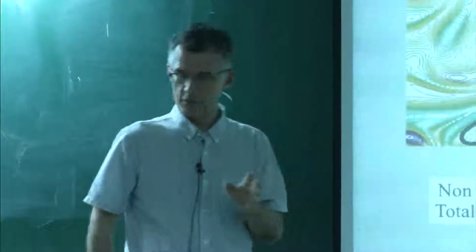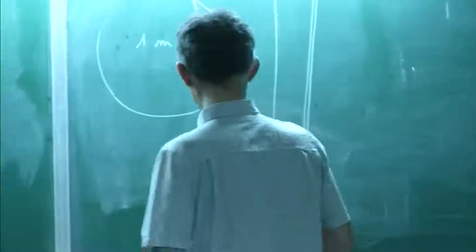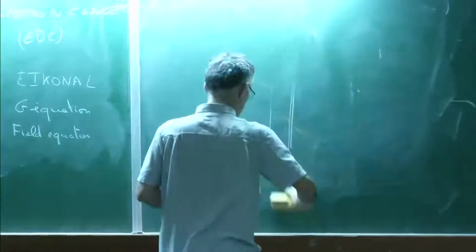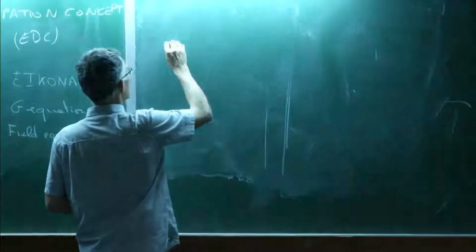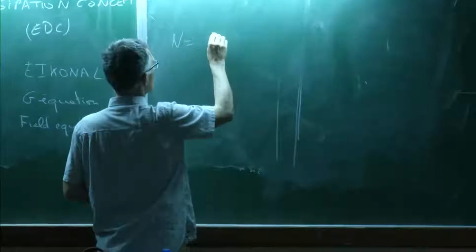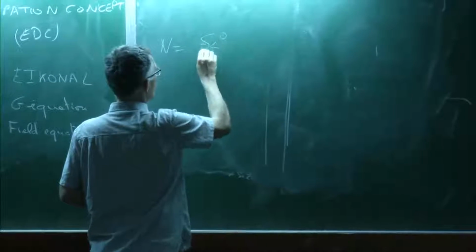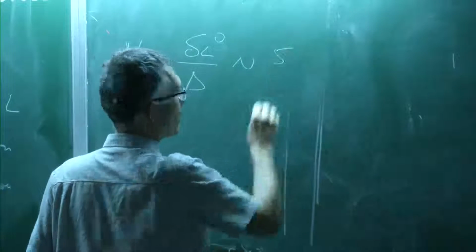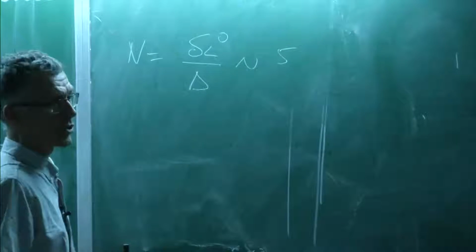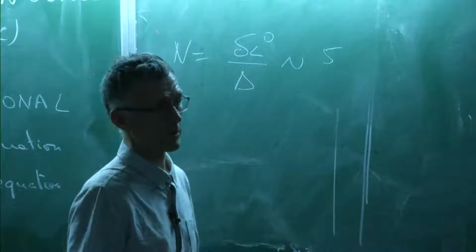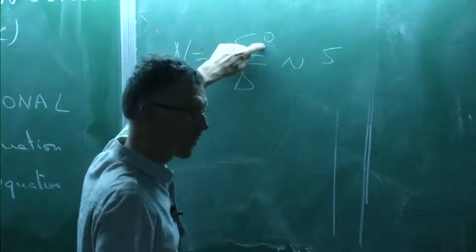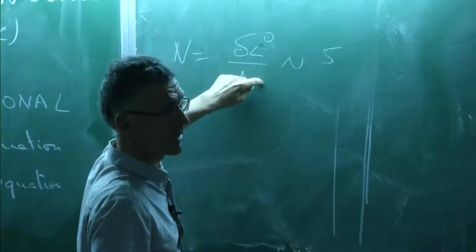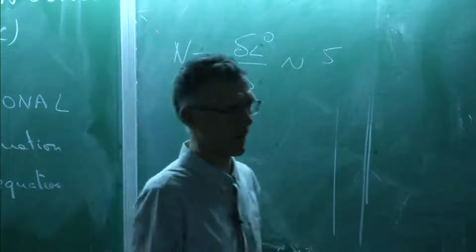Okay, there are many ways to do that. The way we do it now, we have a method where we look at the local grid, and we always impose that we have typically, if this is the flame thickness divided by the local size, we want this to be approximately 5 to 10, which means that we change the thickening as a function of the grid. We compute the local flame thickness, the local size of the grid, and we change F. I will show maps actually of F pretty soon.